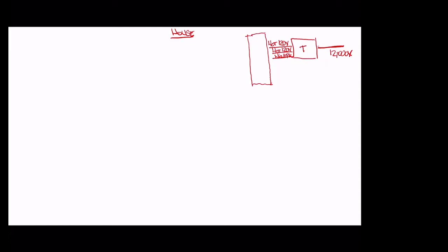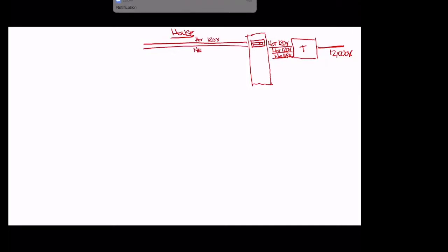So those switches, we'll draw one here. They're a little bit like a tooth. They go way back. You don't see the part that goes back, but it's got a little switch and that one's on. And out of that switch are going to come two wires. There's going to be a hot 120 volt wire, and there's going to be a neutral. All right. Now, this circuit, we'll say it goes to 3 electrical receptacles and 4 light fixtures.